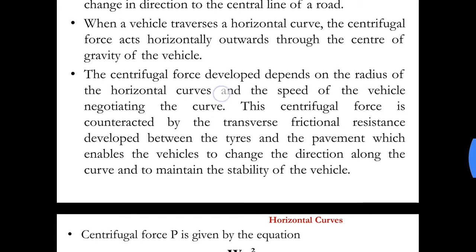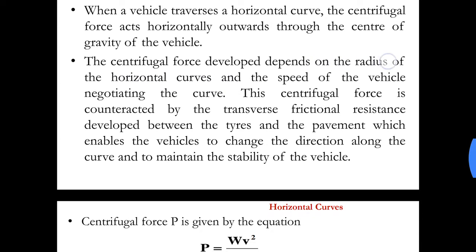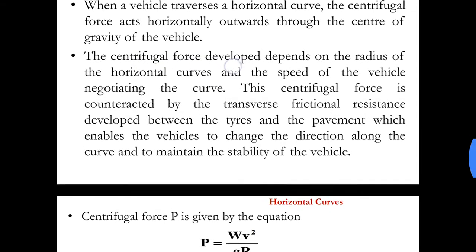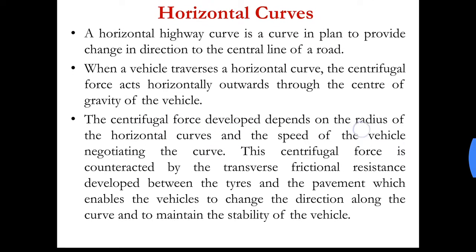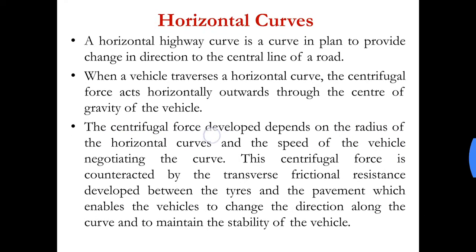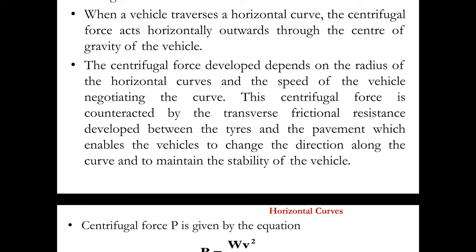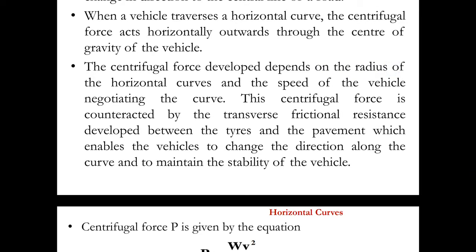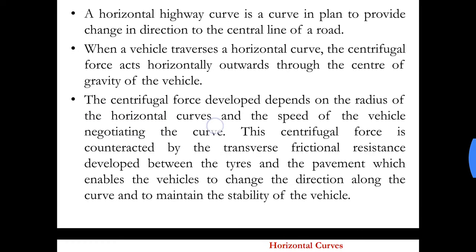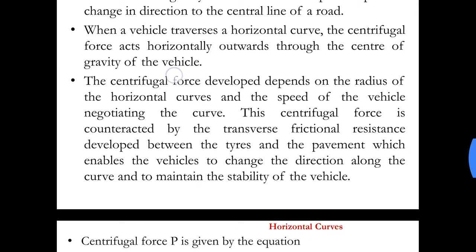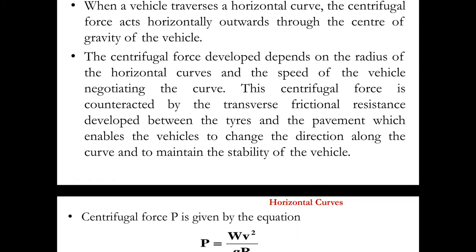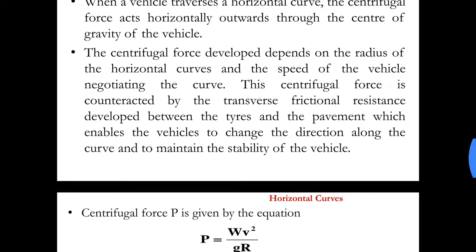If the radius of the horizontal curve is more, then the centrifugal force would be less. You need to imagine this. When the radius is higher, the curve would be less sharp, so it would produce lesser centrifugal force. As the radius reduces, the horizontal curve becomes sharper, and hence the centrifugal force induced would be more, and it also depends on the speed of the vehicle negotiating the curve.